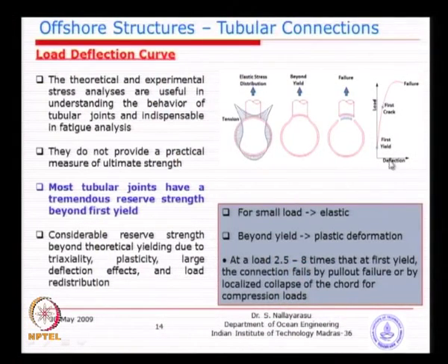Now, we have to decide whether we want to do the design as per 0.6, or 60% of yield. Normally we have designed the members with 0.6 as our allowable stress factor, which I think most of you remember, for bending, axial and shear and so on. We need to decide whether we want to use that kind of concept or we want to go beyond.